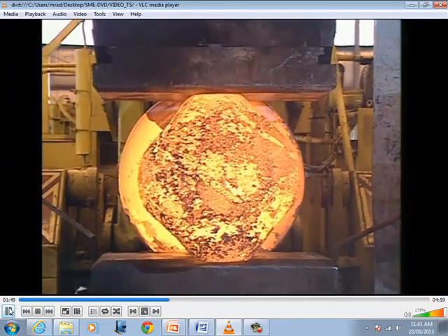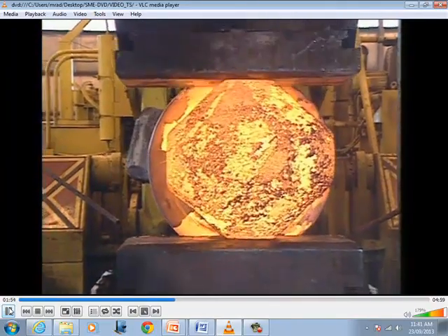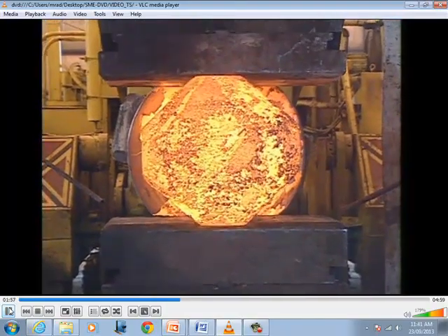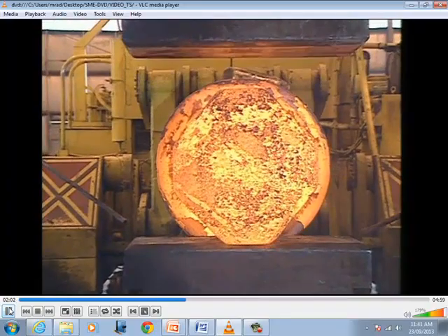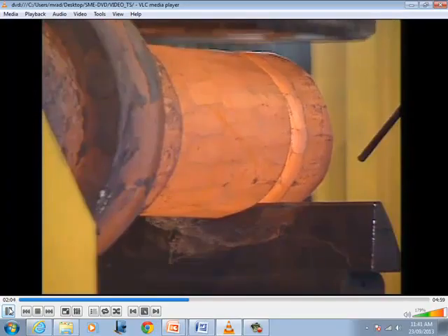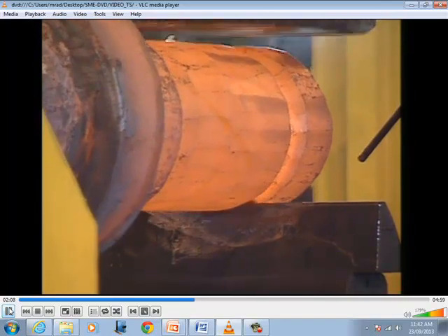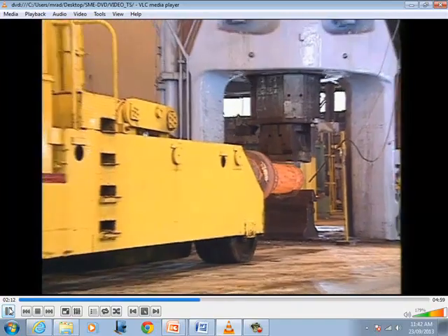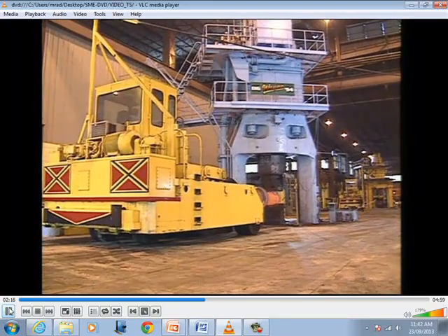Lengthening and upsetting are typically done using multiple impacts as the workpiece is incrementally advanced lengthwise and rotated about its longitudinal axis. There is essentially no limit to the size of forgings that can be made using open die forging. They can range from a few centimeters to 30 meters in length and weigh from a few to up to several 100,000 kilograms.